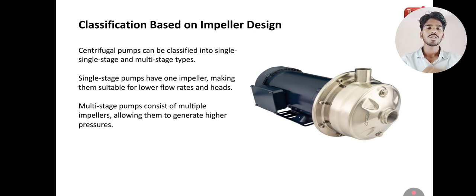See here you can observe that the single-stage centrifugal pump has only one impeller, and it can be used for low discharges and where low force is required, and multi-stage is used for the high force required for pumping water and fluids to an upper level, etc.